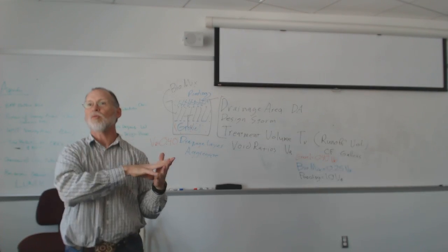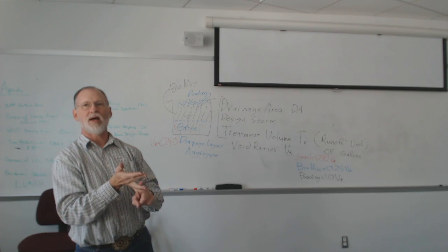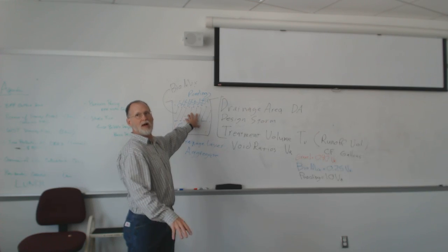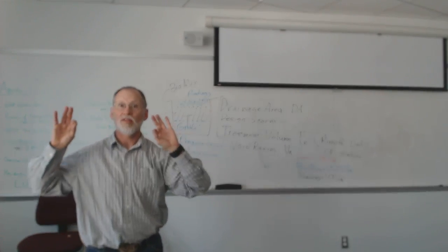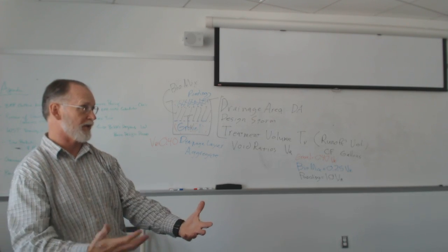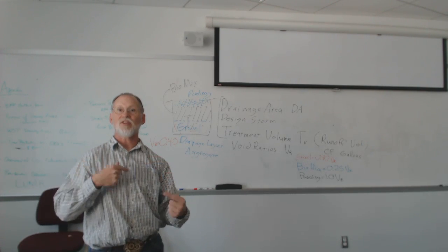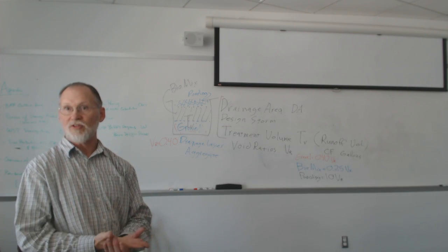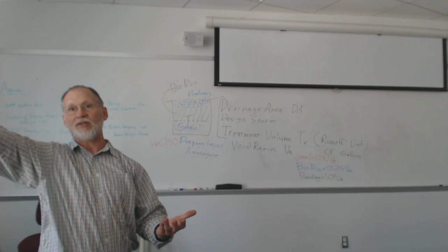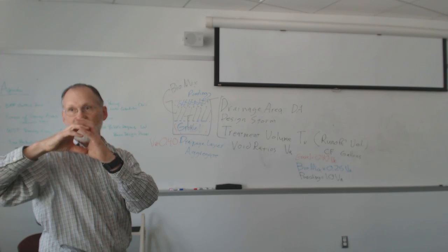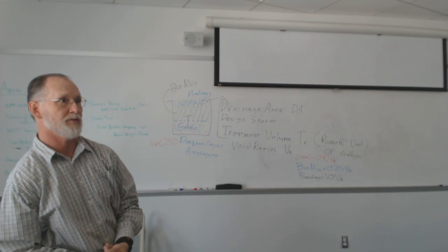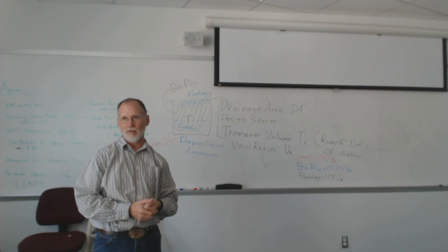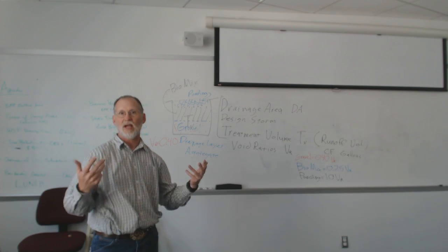We'll design these features at two levels. The first level is to capture the treatment volume. That is for our low-level, everyday, average storms, which is where the vast majority, statistically, of our pollutants are coming from throughout the year. Then we will design them for a larger storm just to make sure that when that 10-year storm hits your facility, it doesn't wash all your plants into your neighbor's yard, or that you don't have such a small pipe that it backs up and floods and goes somewhere unpredictable. So there are two different design features there. One is to protect the rain garden and the property around it from damage when you get that real gully washer.